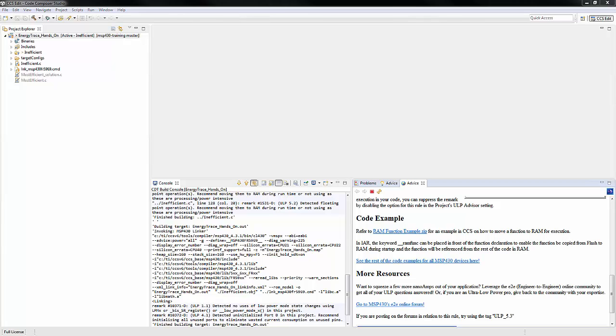So the next step is I want everyone to make sure to prepare your hardware. If you look at your LaunchPad in front of you, I want everyone to make sure you remove the CTS, the RTS, the RXD, and TXD pins, and they are all located on J13 jumpers. These are not needed for our project.